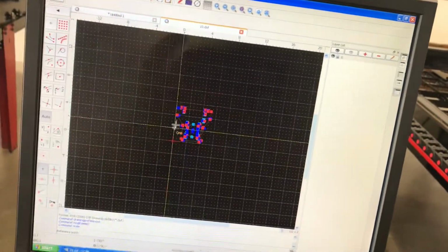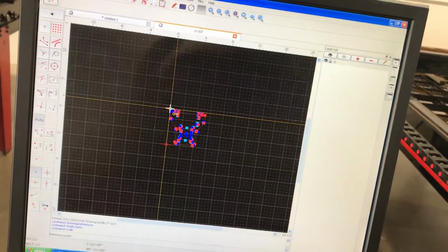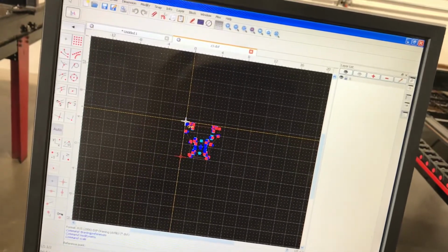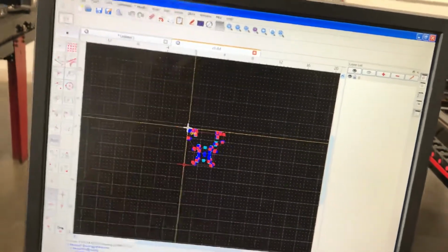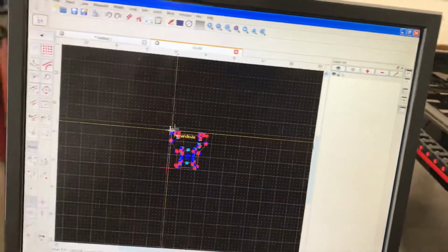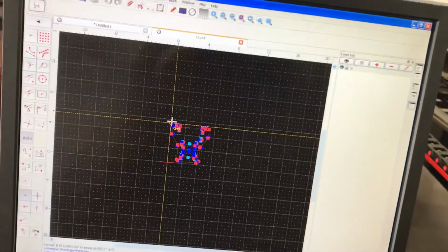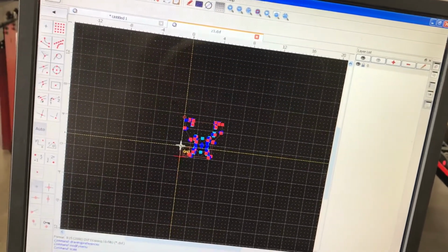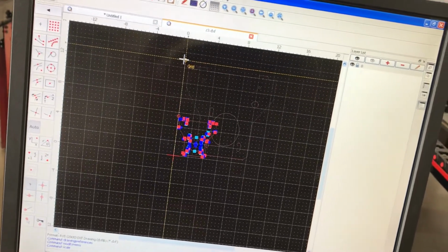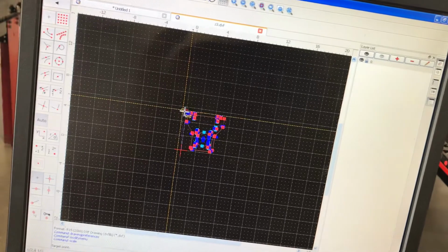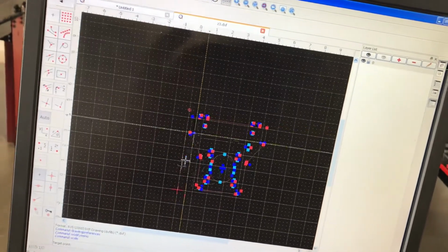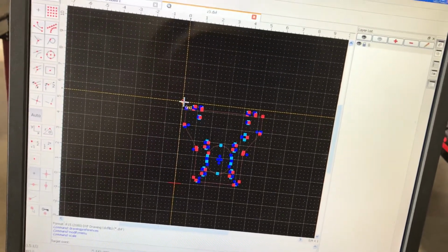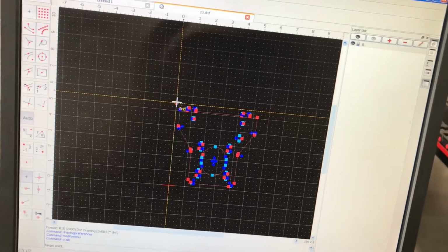I'm going to hit OK, and then I'm going to click here at the top left-hand side of the image as a reference point. So essentially, once I set here, this is from here to here. When I click, that is now 100% of the shape. So this is what the actual shape is. Now I can actually move in by points to scale it exactly how I want to scale it and at what size, based off of this. So it's using this particular reference, this line from bottom left to top left, what I've used as a reference, to determine the actual height and scale of this particular piece.